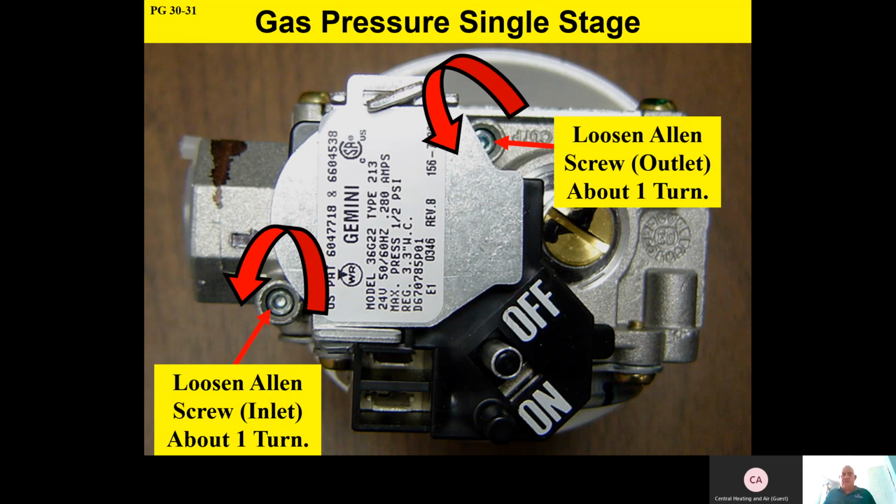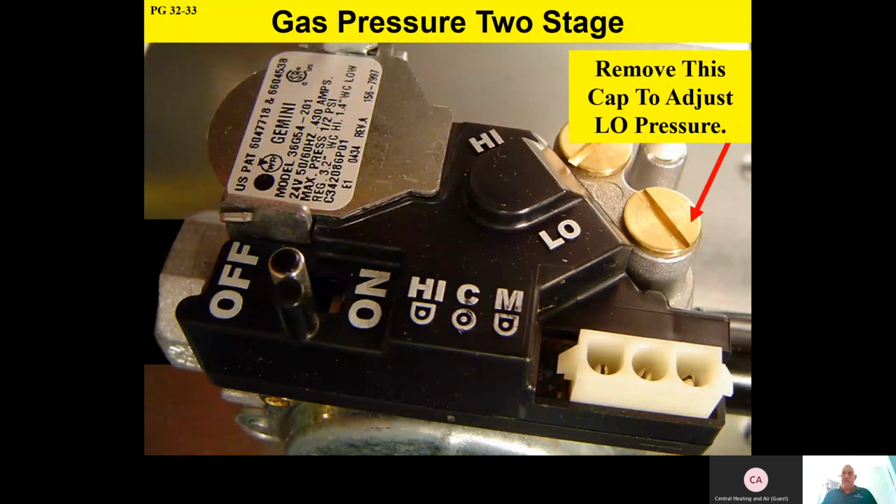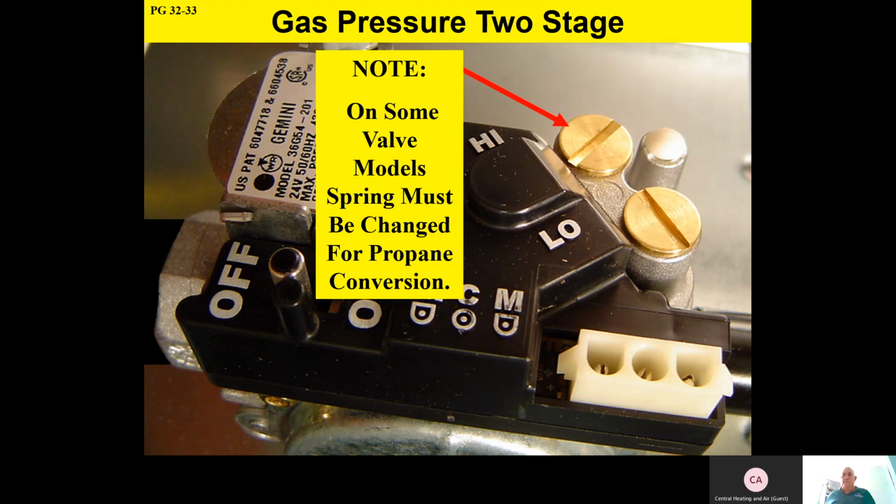And then underneath that brass cap, you can adjust the pressure. Now, it should be noted, team, on a two-stage gas valve, you'll find that information on pages 32 through 33 on your handouts. You're going to have 2 brass caps, one for the low fire, one for the high fire. And it should be noted that on some gas valves, you're going to have to change a spring underneath the high fire for propane conversion. Please make a note of this as well while I'm thinking about propane.